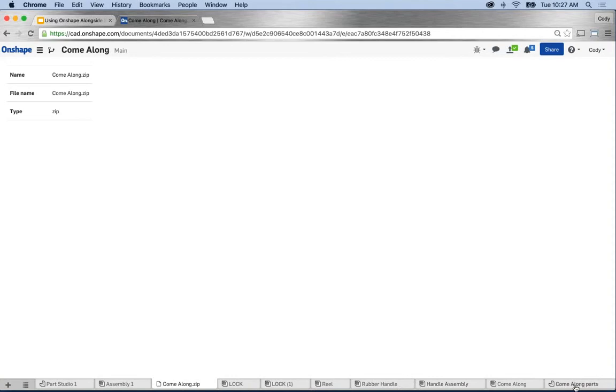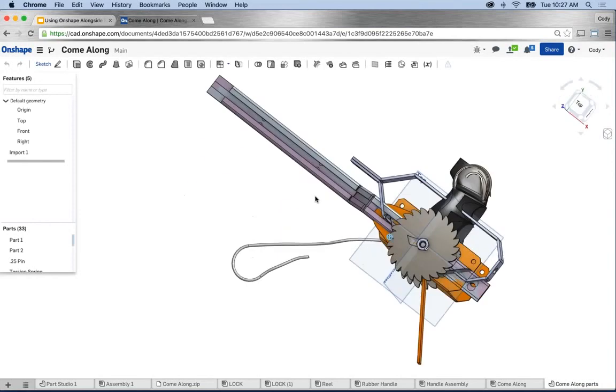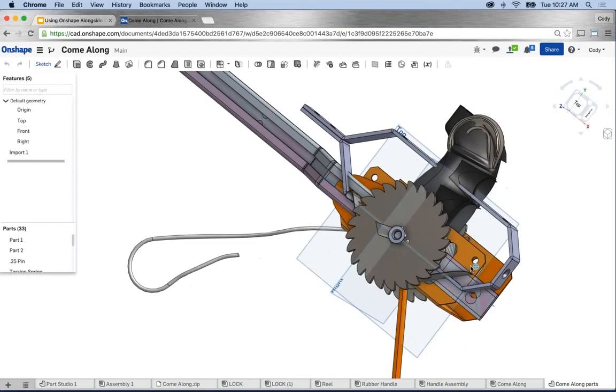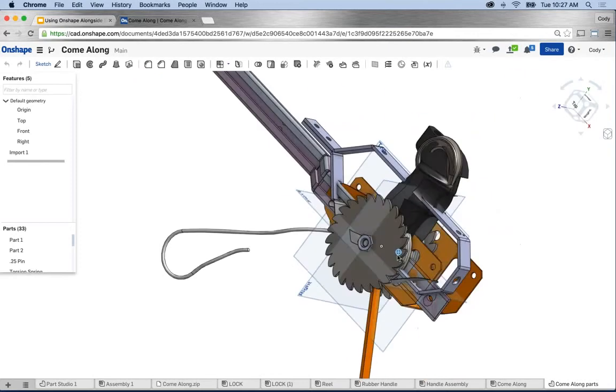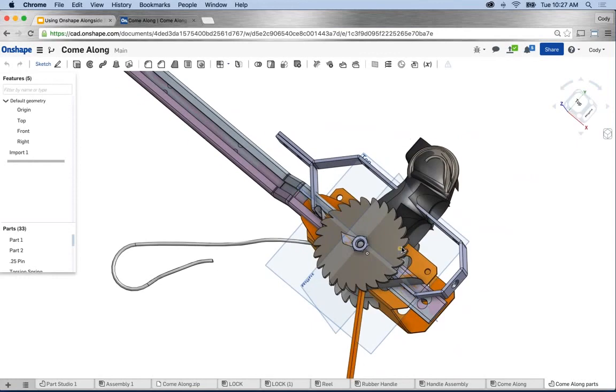Now you also have a tab for all the parts. So if I left click this tab here, you'll see all the parts of this assembly are brought together. The key thing I want to point out with this is they're imported into this Part Studio in the orientation they were modeled. So it looks like all the parts are sitting on top of each other, and they are. But the reason for that is how they were modeled. They're all modeled in a bottom-up method, right? If I had modeled this in a top-down method where all the parts are relative to the origin in that way, they'd come in imported that way. But there are some things we can do to simplify this process.